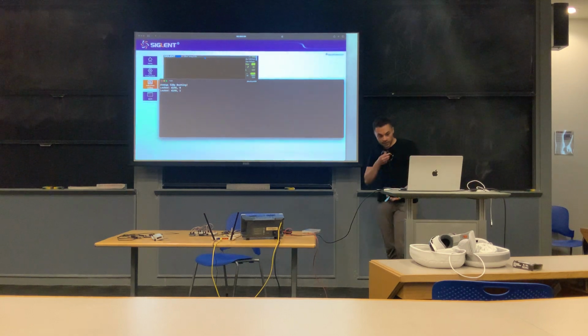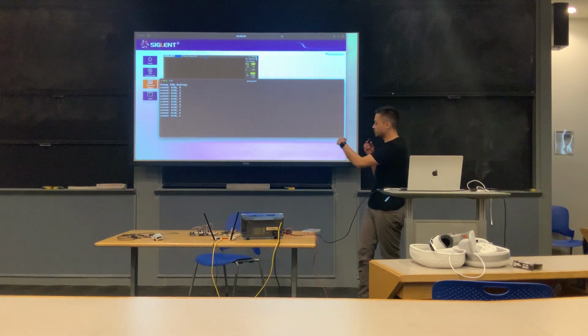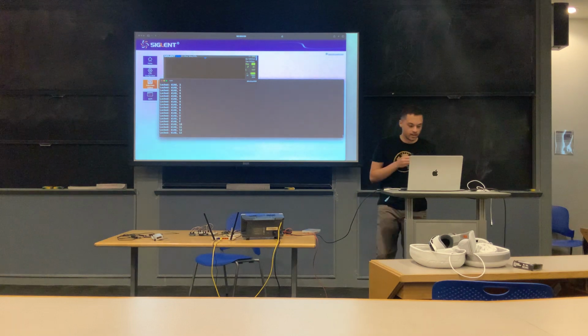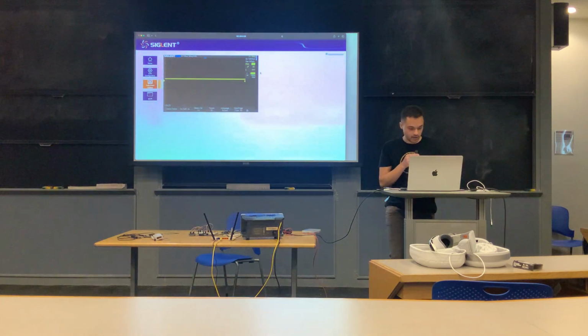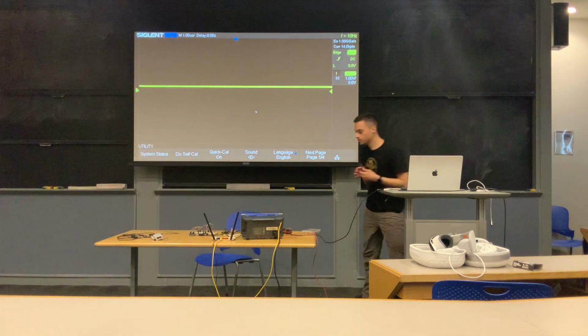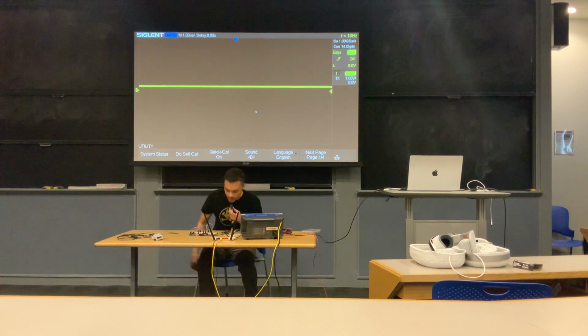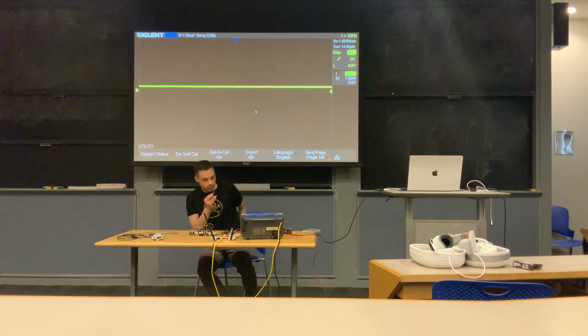All right, so we're connected to the chip, and we can see it boots up, and it just keeps printing, we're locked, whatever. And so you can let this run for all time, it will never break the loop. So let's go ahead and switch over to the oscilloscope and see what that clock signal looks like. So here we are in the scope, and I'm going to go ahead and connect into the clock pin.